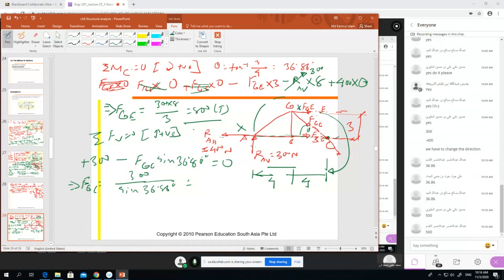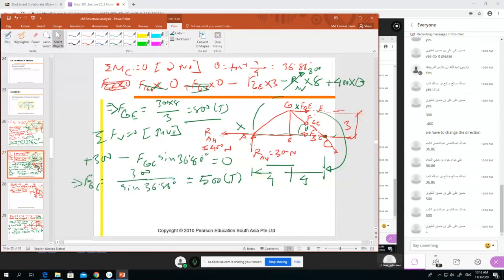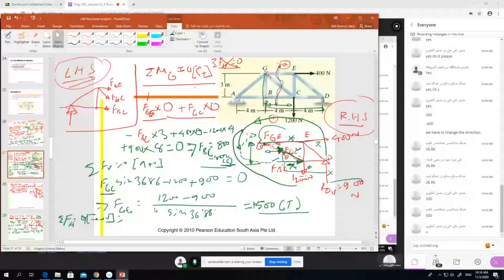Plus or minus? Tell me. Plus. So tension. So FGC, we got 500 tension. Let's check with our previous result. Our left hand side, FGC, right? FGC 500 plus 500 tension. Okay, so the answer is correct, right? The answer is the same.